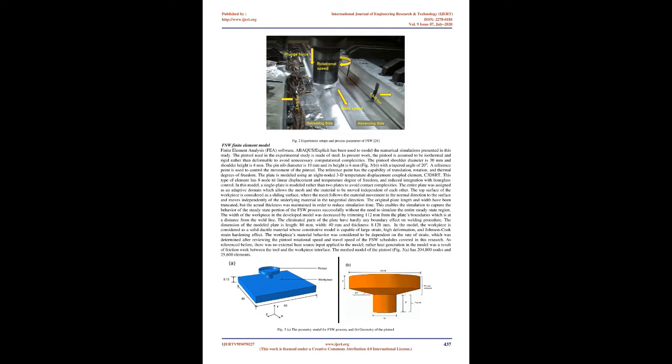However, in the work of Zhang et al. 30, only a single weld schedule has been analyzed to observe the effect of process parameters on the friction and the plastic energy. Therefore the focus of this paper is to compare the Coulomb and the modified Coulomb friction models by studying the effect of process parameters. The models used in the current work will help understand how the process parameters can influence temperature, friction, and plastic energies. During FSW, there are several interactions between process parameters known to affect the overall quality of the weld that need to be considered, such as pintool rotational speed, welding speed, and the plunge rate.